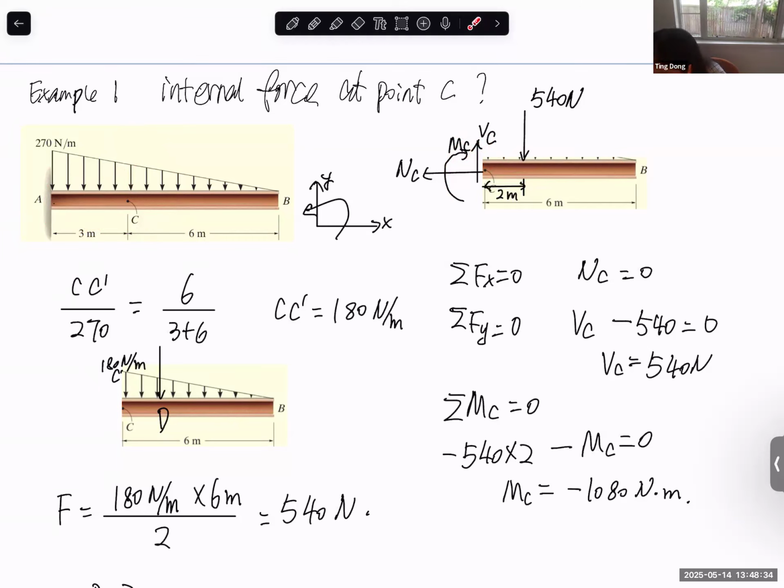It has to do with the fact that the tension on the right-hand side will give you a counterclockwise moment. It's tension. Okay, I don't understand, what tension here gives you a moment? If it's tension, it passes through the point you are calculating, so there's no moment. The axial force does not generate moment if you choose C or B or D, because the axial force passes through the C point, B point, and D point. There's no moment generated by the axial force.